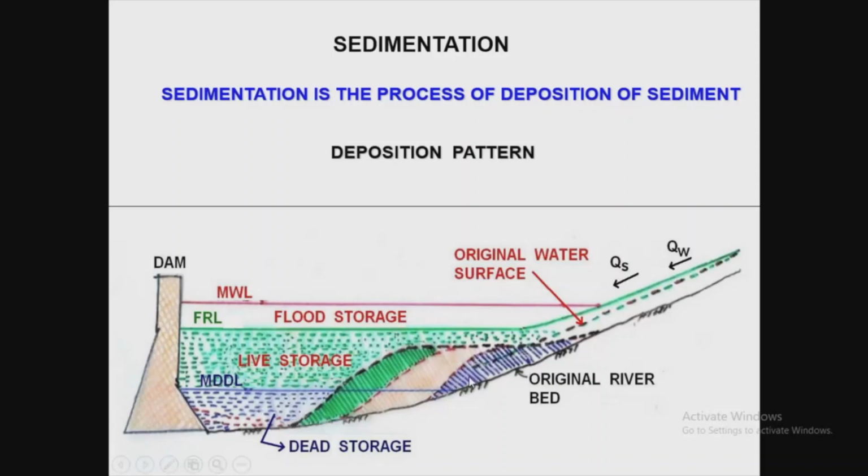So the concept that our whole sediment will go and deposit below MDDL is correct, but it's not correct with respect to time, because it takes time to displace a wedge from live storage to below MDDL. Because if this wedge is deposited and solidified, then it will permanently encroach on the capacity of the reservoir. You can see around 30% of the capacity of the reservoir is encroached by this in the live storage. So this is very alarming, and this capacity we have to assess.